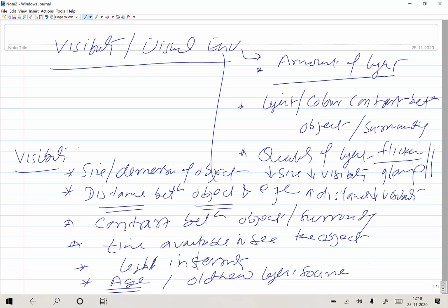There may be a drop of 10 to 25% in lighting capacity with time. So it is not good enough to consider that you have installed a light source of the desired capacity and that it will continue to supply the same.